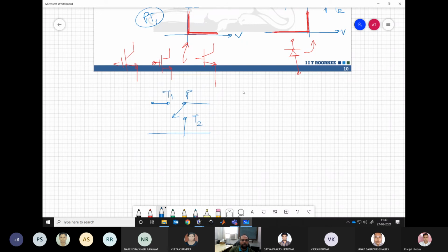this pole T1 and T2, can be realized in this manner. Let's say I take a BJT. So this is our pole which is always connected to the inductor and then either it connects to throw 1 or it connects to throw 2. These are the devices which are in place to realize the SPDT switch. Now we can say that our buck converter is realized completely with these power electronic devices.